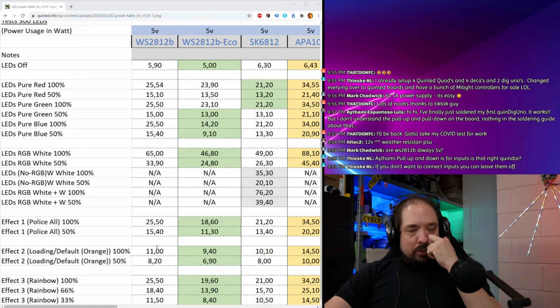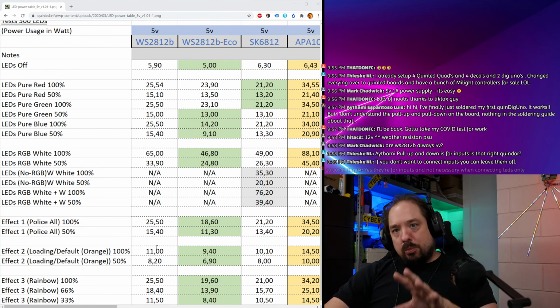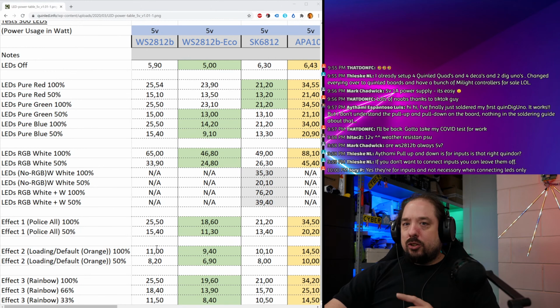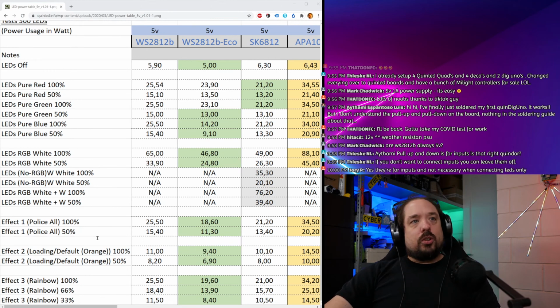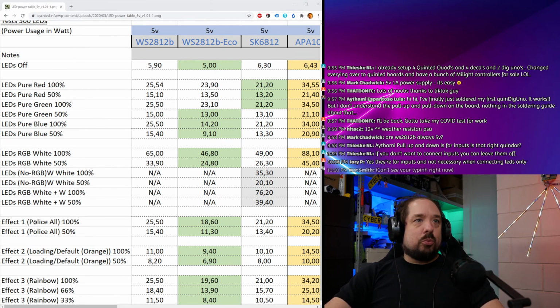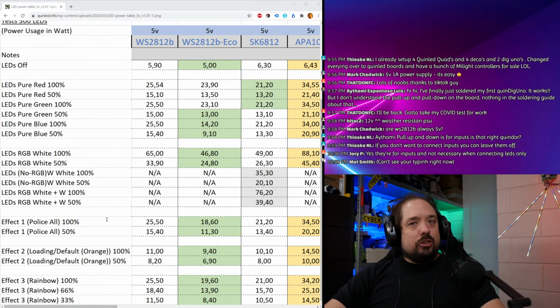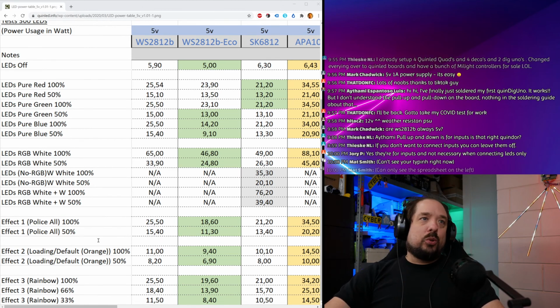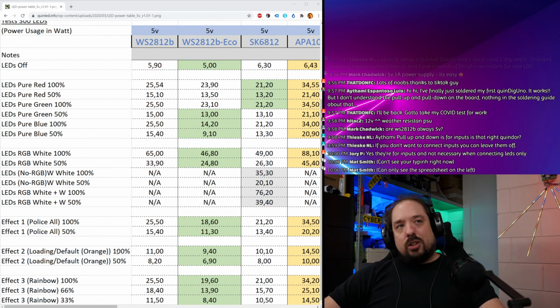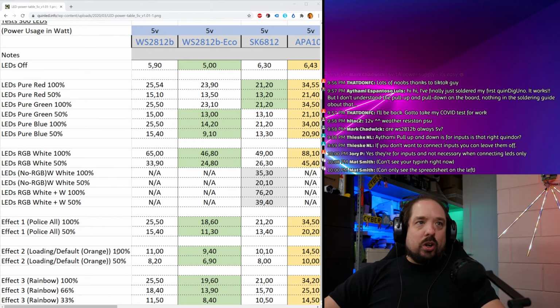So, when doing power injection, 1 point on the LED strip can generally carry about 3 to 4 amps. So, if we need 6.5 amps, that would mean if we wanted to run these 150 LEDs per meter, or 150 LEDs in total, we need 2 injection points. But we calculated on the safe side. We can do it on a less safe side because we don't want to do all that wiring.